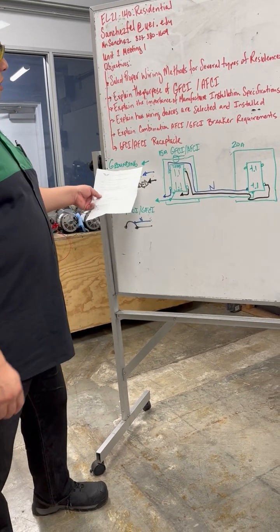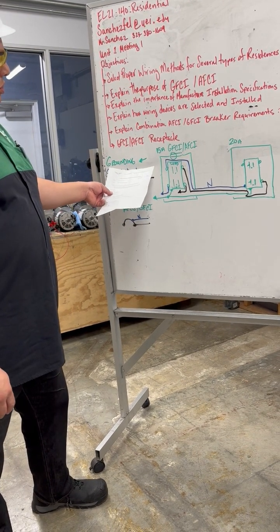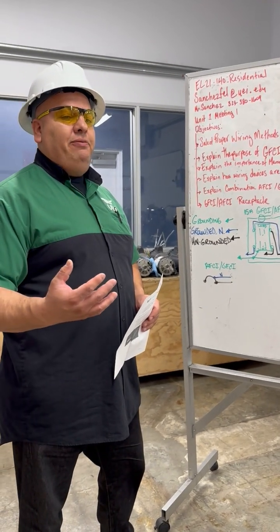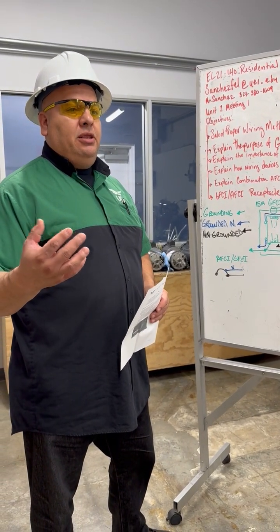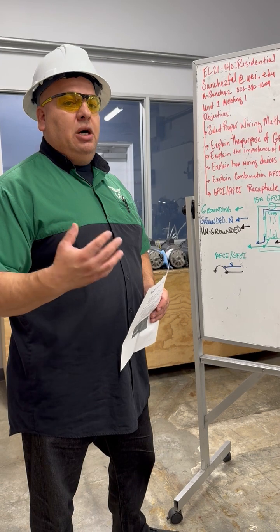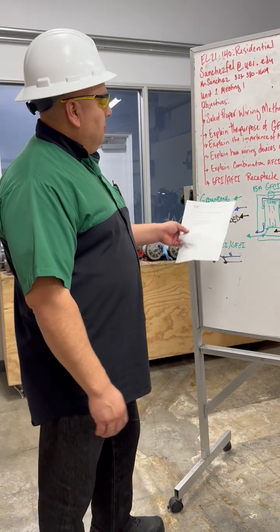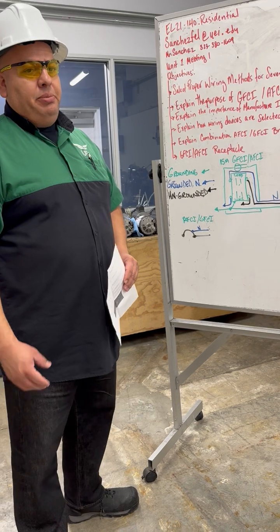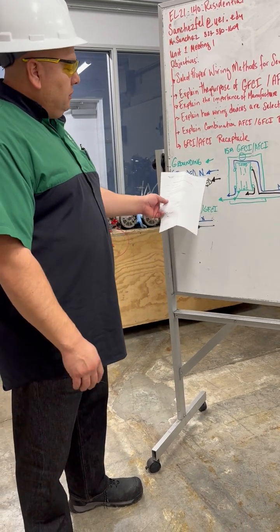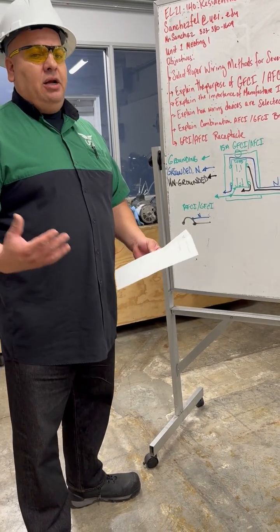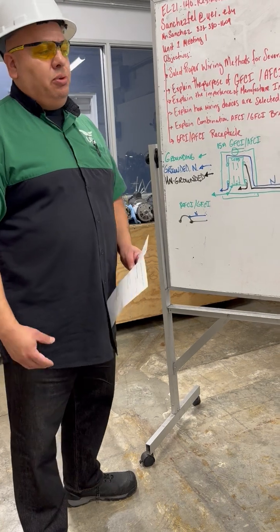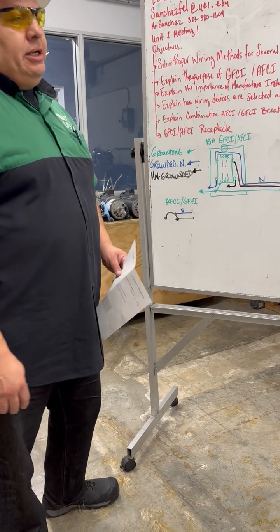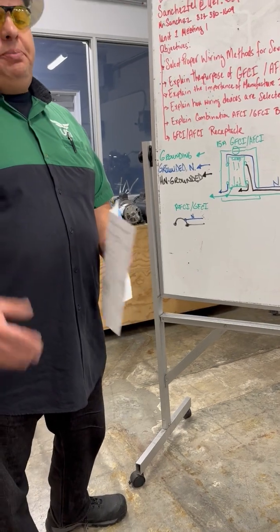So I always make it a point to point out to them for every class, because obviously we're always receiving newer students than the more experienced ones as we continue on through core. Explaining the turns, straight turns, grounding conductor, bare copper, green, grounded neutral, white. Obviously, I utilize blue on the board because of the whiteboard concept. And then we have the ungrounded conductors, which could be black and red typically.